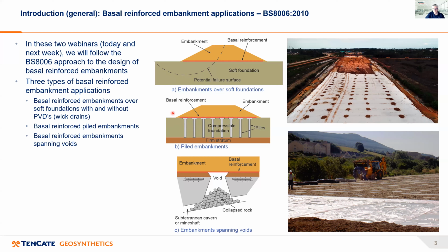Again, the basal reinforcement on top and the embankment built on top of that. And you can see an example there in the bottom right photograph. There you can see the pile caps at the surface, the basal reinforcement, and then starting to place the embankment fill. And then there is a third application, basal reinforced embankments which span across voids.